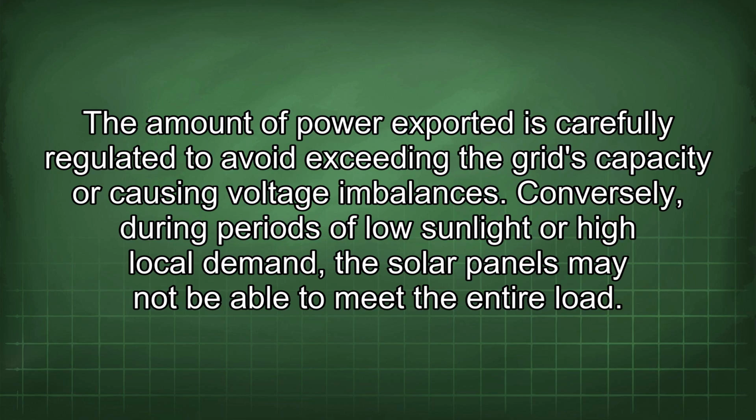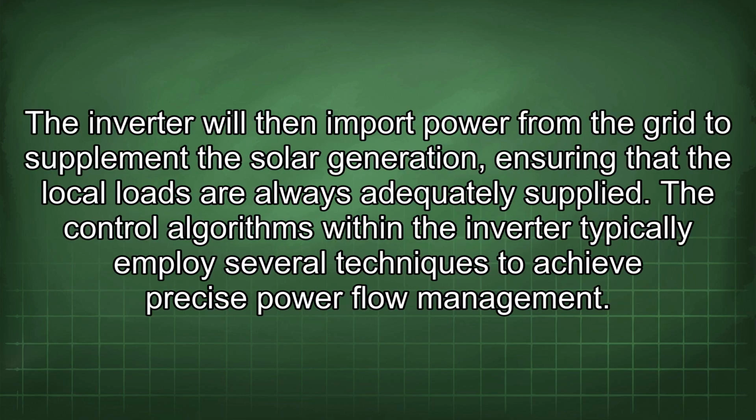Conversely, during periods of low sunlight or high local demand, the solar panels may not be able to meet the entire load. The inverter will then import power from the grid to supplement the solar generation, ensuring that the local loads are always adequately supplied.